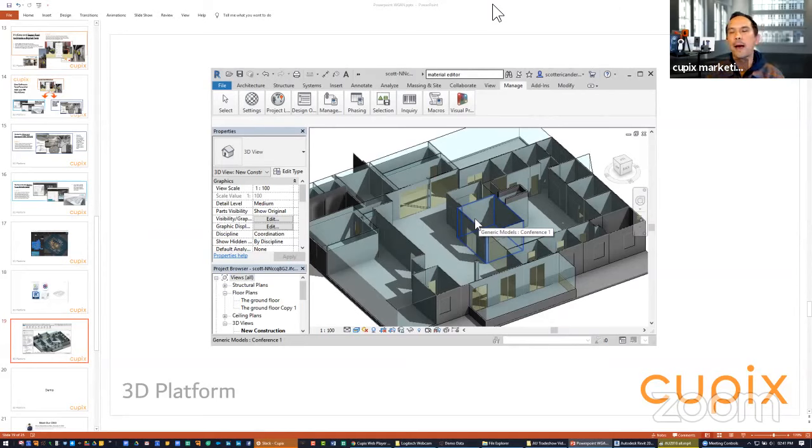Or we can talk about how accurate the Cupix tour is that we create. So it's a two-step type of question. When you force things to be rectangular, when you force things to be vertical, when you force 90-degree angles, you're always going to introduce some sort of error, because you're going for that model that's easy to work with, easy to build new walls, easy to render and calculate volumes from. So no matter what the process is, even if you're dealing with 1 billion points or a Matterport scan, or doing a hand-drawn drawing, you're always going to go for this rectangular, vertical, 90-degree type of model.